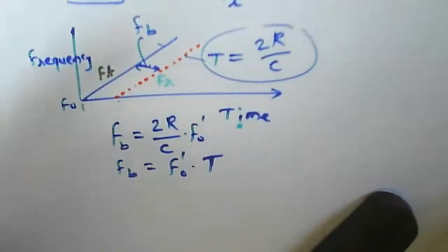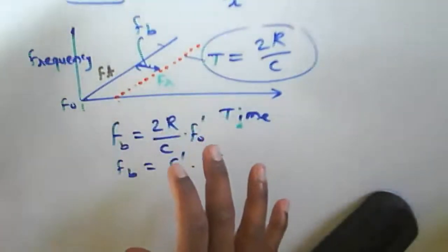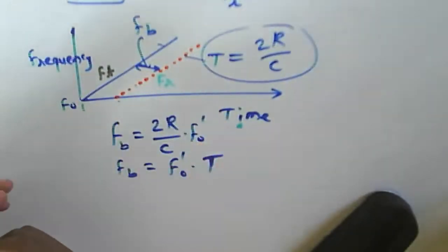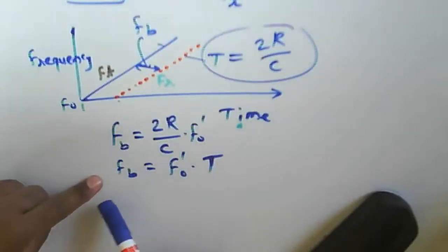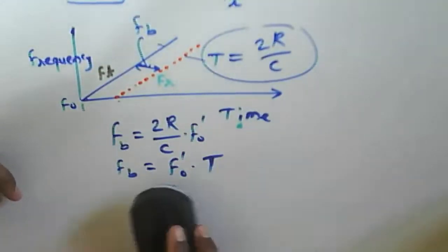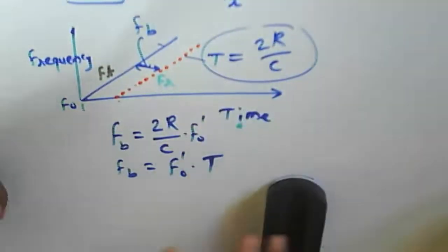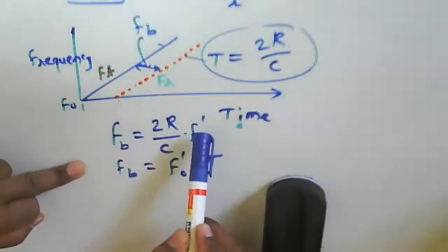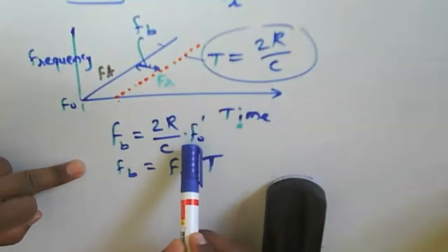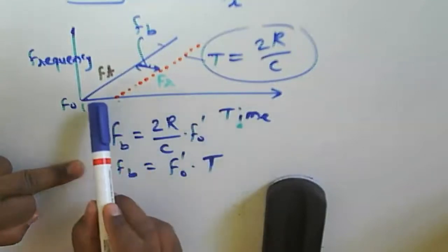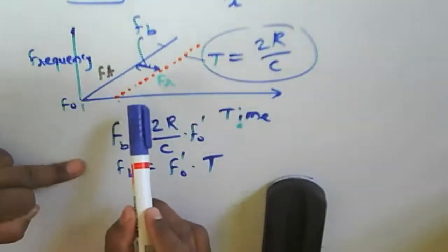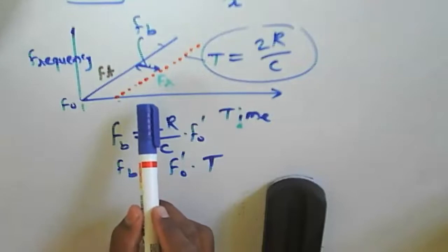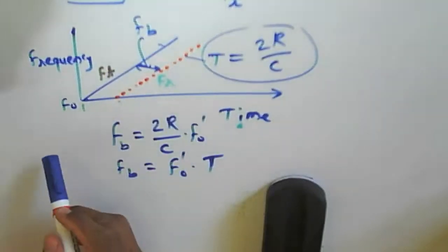Now we need to know what type of modulation we have, whether it is sawtooth or triangular. According to that, the beat frequency will change. So instead of writing in this way with respect to a carrier here, we can write the modulation bandwidth and the modulation period.